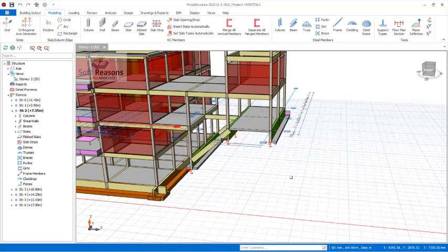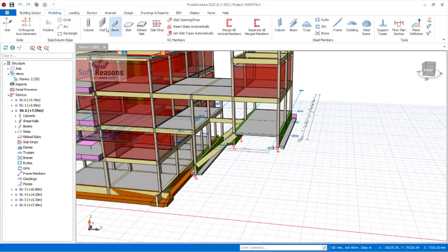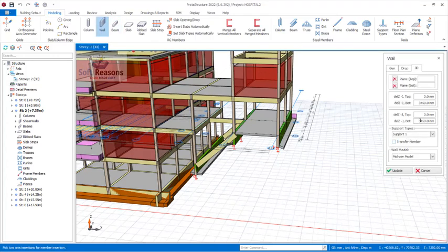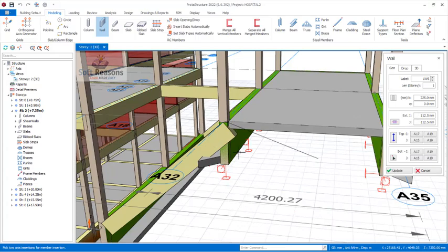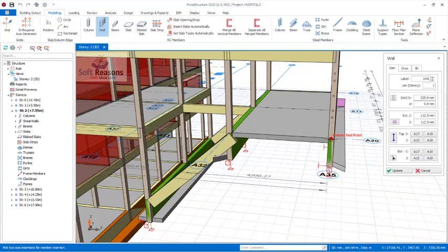All right, then if I select the shear wall right away, and for instance I did not apply this, what happens is, let's say I have this bottom story height to be 0, just like this. I get to the general, and then I have my shear wall to be 225. The eccentricity is 112.5. So I pick this point all the way here. I pick this other point.